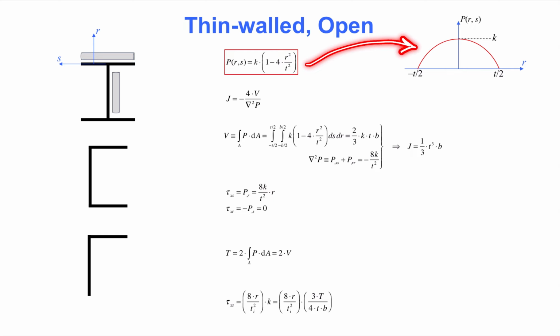Notice that the amplitude of the stress function is k, and that it runs from minus t/2 to plus t/2. In words, this is a quadratic pillow with magnitude k that follows the longitudinal direction of all cross-section parts. Wherever a cross-section part ends, there is a minor error. The stress function is not zero at that short edge, which violates an important boundary condition explained in the video